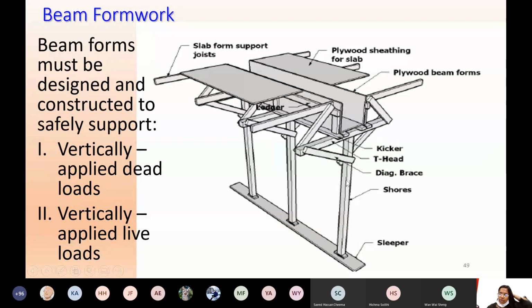Shores, right? They call this a shore. The pole is called a shore here, and these are the sleepers. These shores or poles are resting on the sleepers. So they use three shores. Generally, the spacing should be 1 meter, 1.5 the maximum. 1 meter, 1.5 is the spacing for any type of beam, right? For normal 3 meter high buildings, 1 meter spacing is necessary.